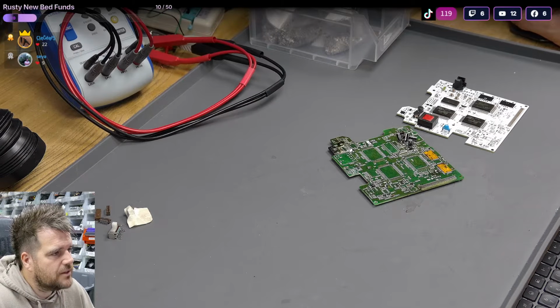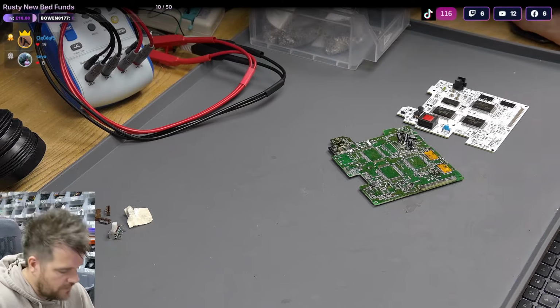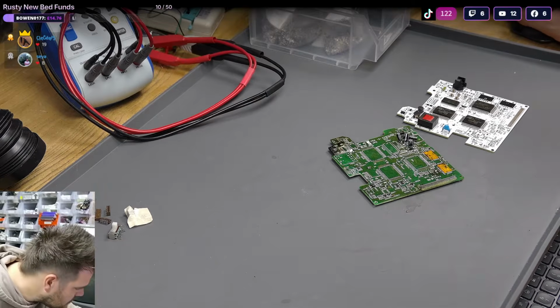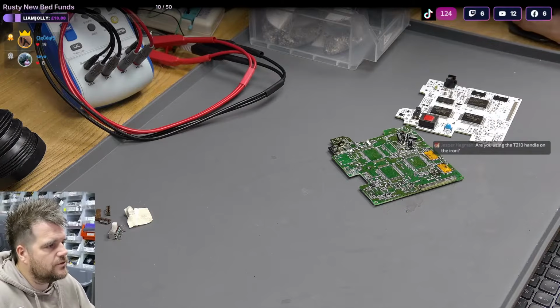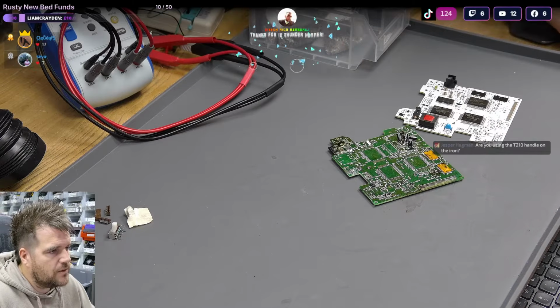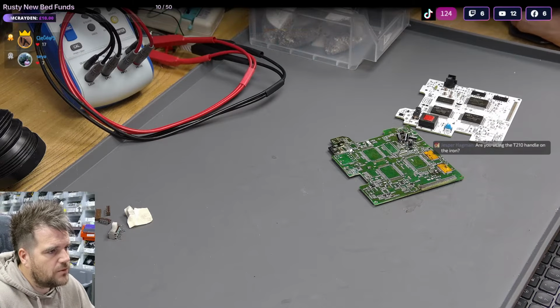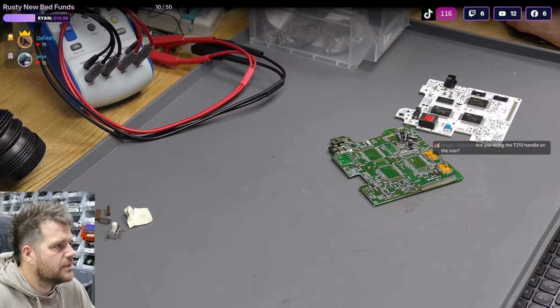Alright, so I'm just going to scan through the desktop PC Engine schematic, just in general looking for some caps that are very low. I don't know where this is at. Oh, it's going to be the crystal. It's right by the crystal. So if I look at the crystal circuit on the PC Engine, although that's quite high for a crystal capacitor, it's almost likely going to be related to that crystal. So this is going to be pretty important to get right, if so.